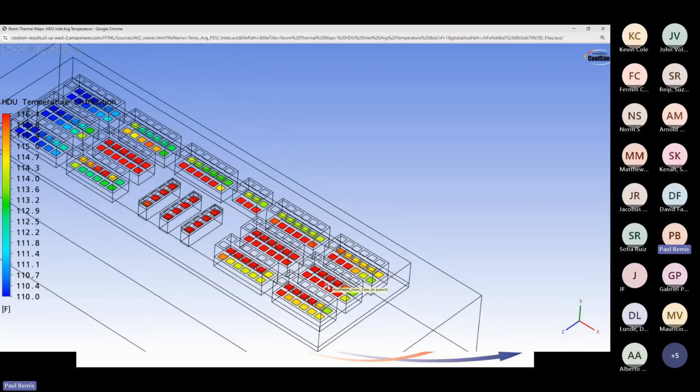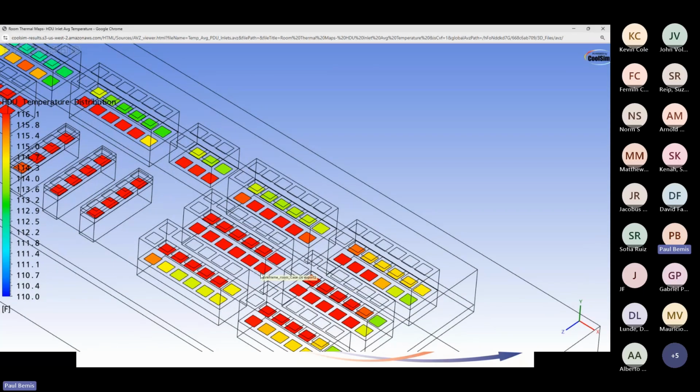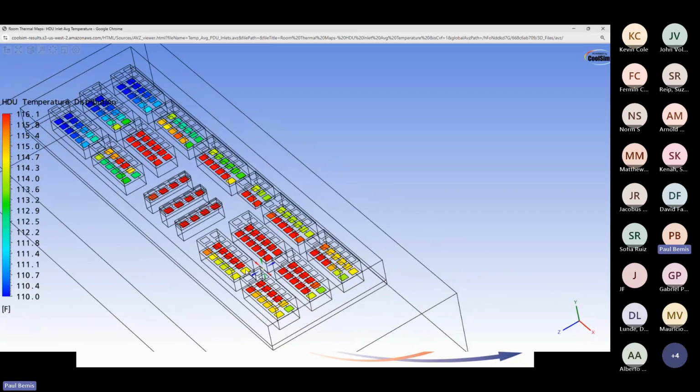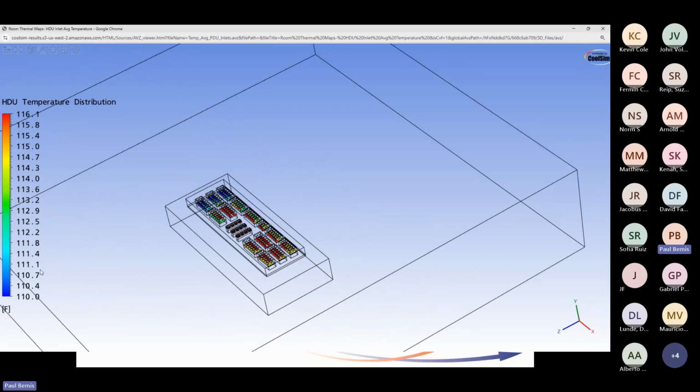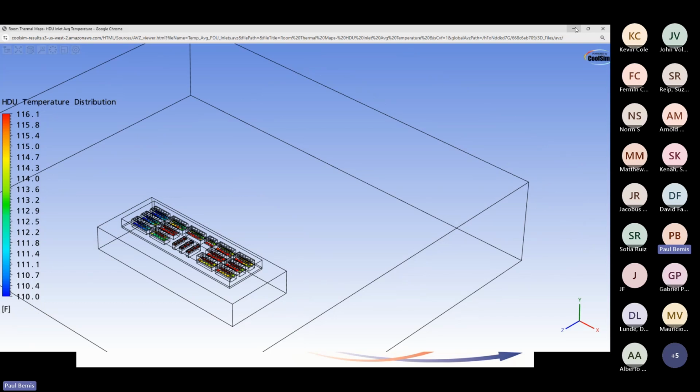But this is exactly what you're interested in. This is the most important shot right here, the average chiller inlet temperature as a function of wind condition. Now we're only looking at one wind condition with one temperature. That's why you want something that runs fairly quickly and is fairly cost effective to use so that you can do multiple of these. CoolSim's quite a cost-effective, I would argue, the most cost-effective solution for doing this kind of thing. Run times on this run right here took me 30, 40 minutes to run. Doesn't take very long to run. And you can get some good insight about what's happening with your model.